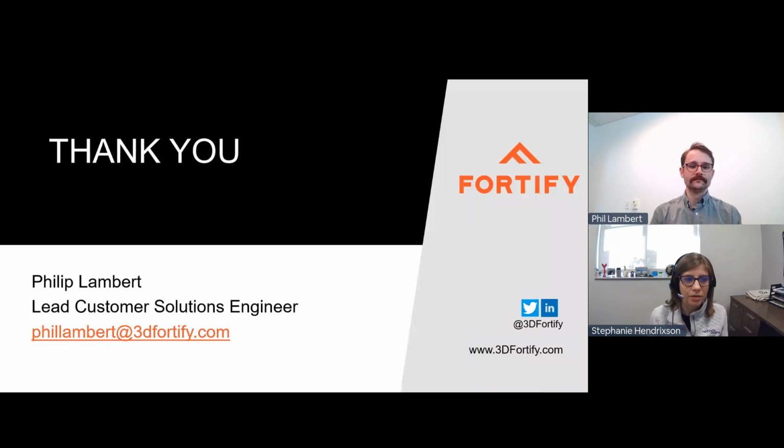Can you talk about other materials that you've developed internally using the Flux Developer toolset? Yeah, all of our materials. We have another material that we've been printing for a few years now called digital tooling resin. That's a material that's filled with a small volume percentage of an additive that we leverage to do alignment for our injection mold tooling applications. That system, I should say, has a very high heat deflection temperature and a very high strength and high stiffness, the types of things we need for injection mold tooling. And so that's one system we developed on Flux Developer.